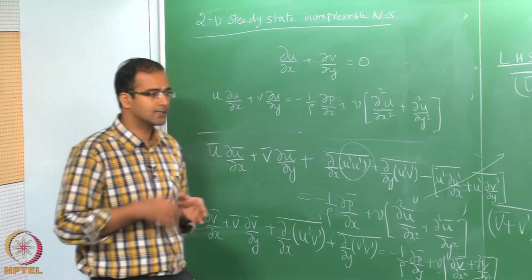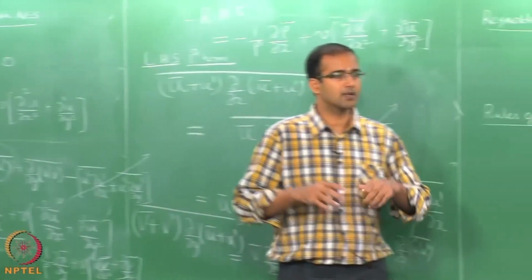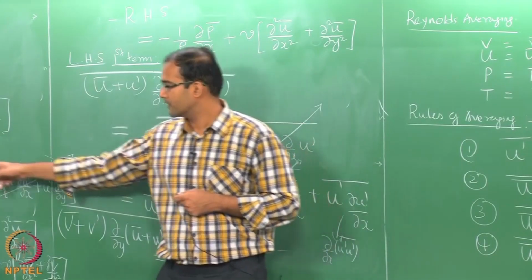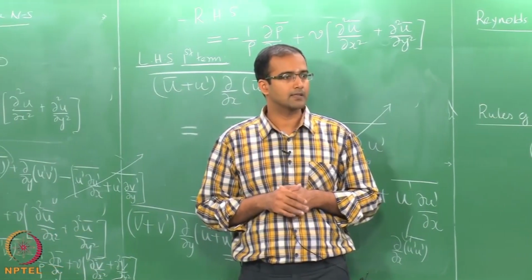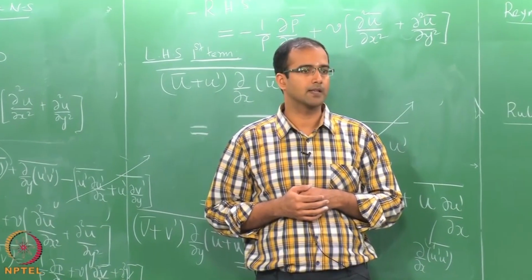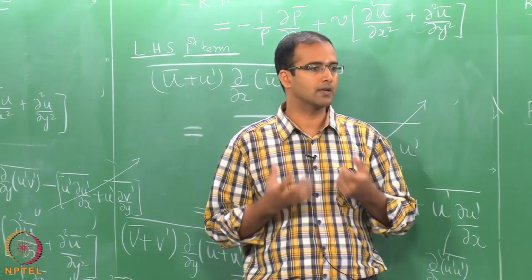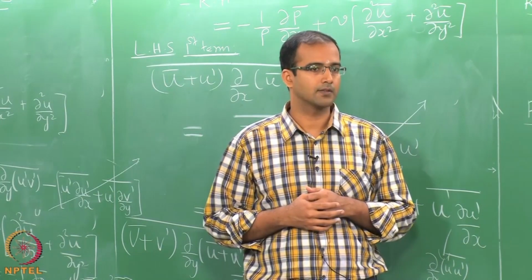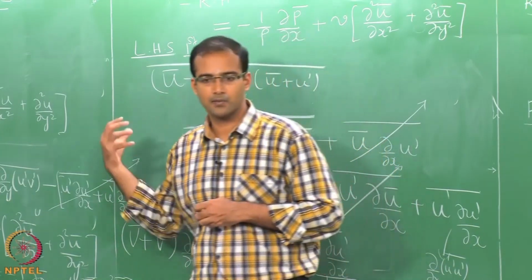So it seems that there is an additional stress coming in turbulence, but it originates from the inertial terms, and that is why when they are taken to the other side they are given a negative sign, because they enhance the momentum. They are not stresses in the conventional sense that impede the flow. They are the ones which actually promote the exchange of momentum and energy. Therefore they have a negative sign because they originate from the inertial terms. These are called turbulent stresses.